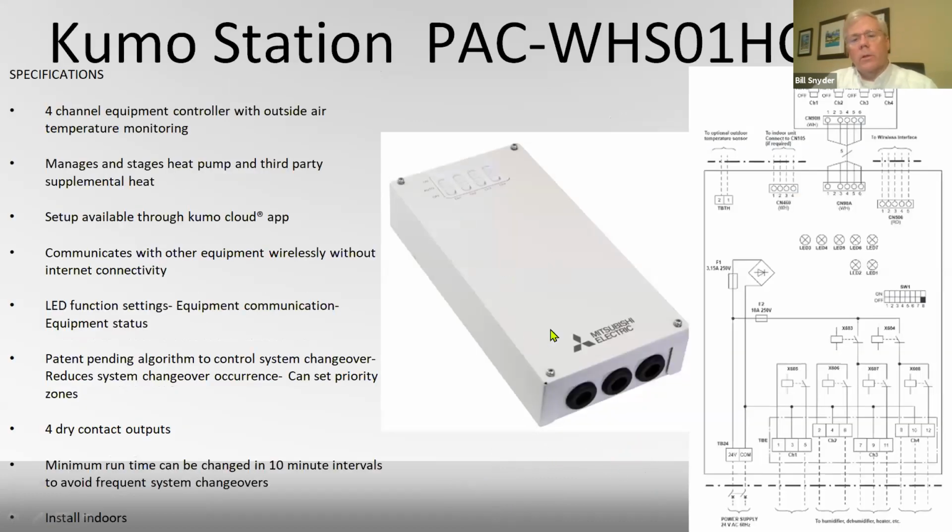This is basically a little relay panel that you can put an outdoor air temperature sensor on and do if-this-then-that type control here. There are 4 relays in there.